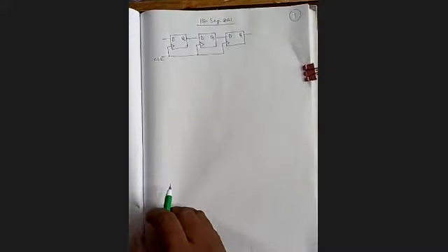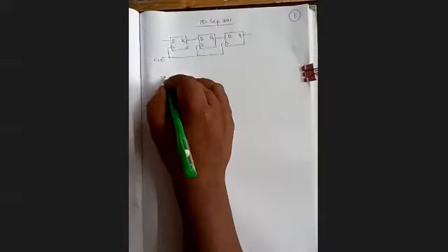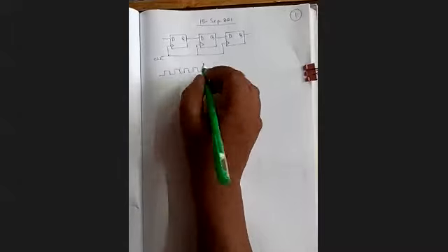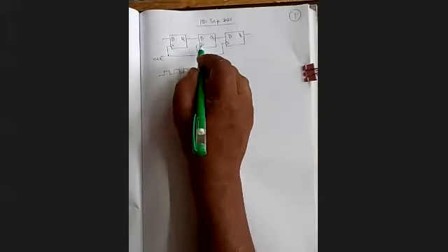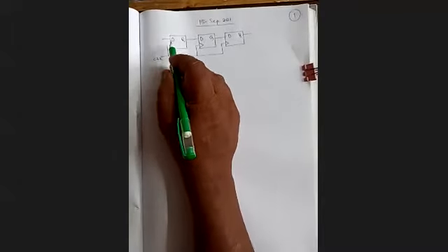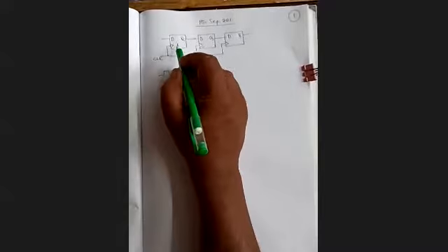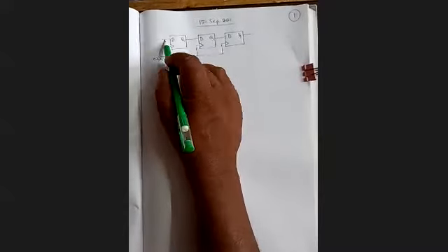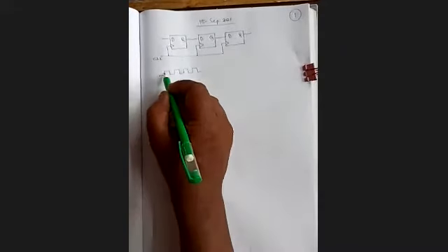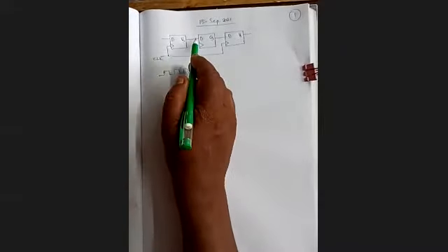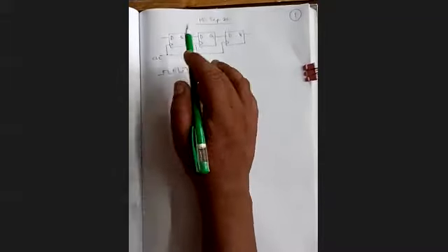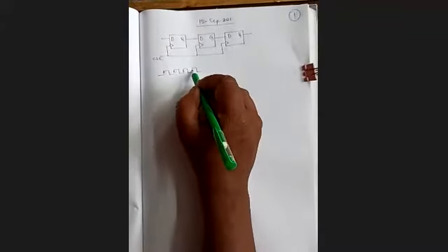Now what happens? This clock is just a square wave pulse, a pulse train, and the edge here is a positive edge, or rising edge. So at every rising edge, the flip-flop will be active and the D input will go to the Q output. At the next rising edge, another input of the flip-flop will go to the output. This happens at every rising edge.